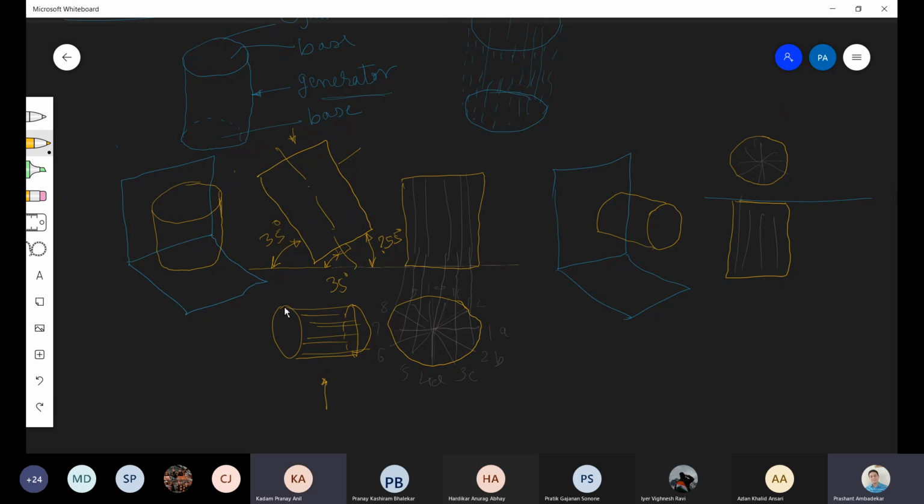Yes. Now, in order to draw this ellipse, you need points, and these points are these 12 points. That makes it an ellipse. Okay, so that's why we need points, and these points are obtained by dividing the circle and then projecting it. I hope it is clear, but it will be clearer when we actually solve it.